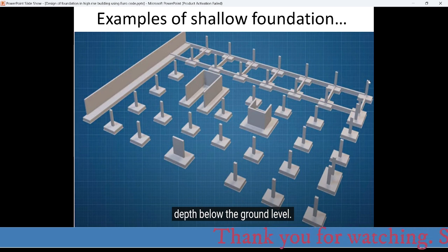All the columns closer to the property lines are placed at the line of the property. Here we have a footing, and this footing cannot be extended beyond the property line. So the column is placed at the edge of the footing, and there is a higher eccentricity problem here.